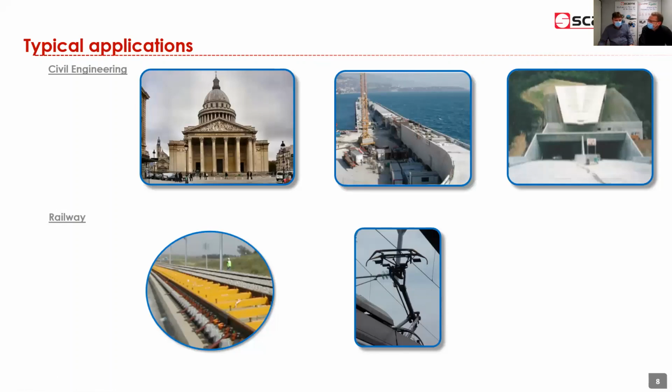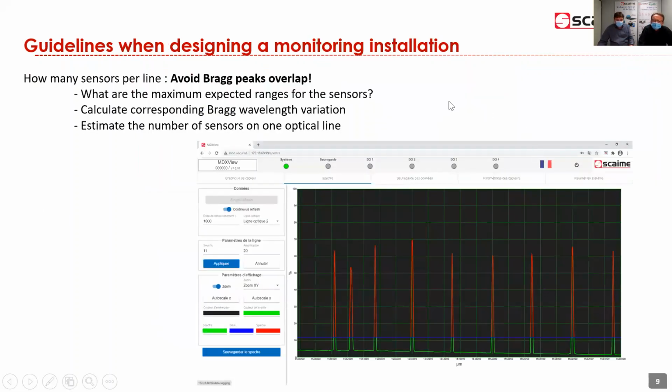Very disturbed electrically, yes, because a lot of the power is passing through the pantograph itself, so the sensors are bonded onto the copper part. So only fiber optic sensors can solve the problem here. Otherwise it would be very difficult, as you would have to run very shielded cables very far from this part. So it's not really possible.